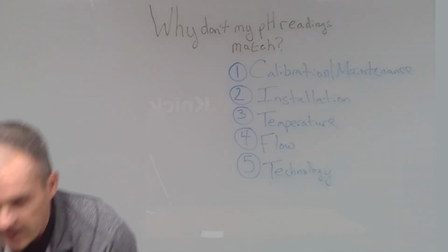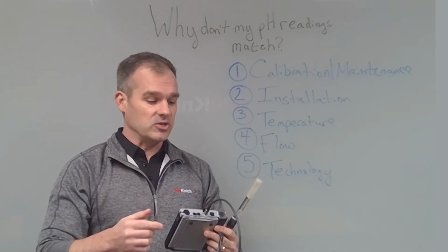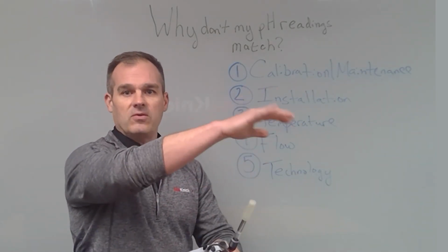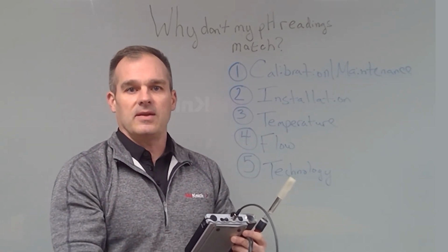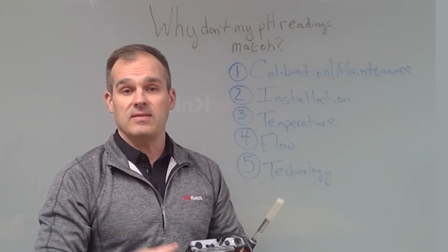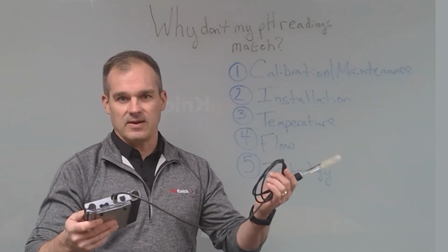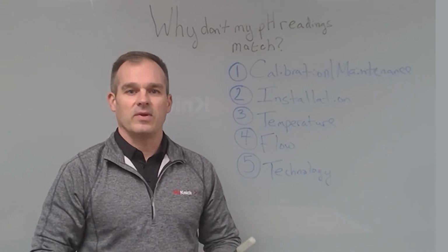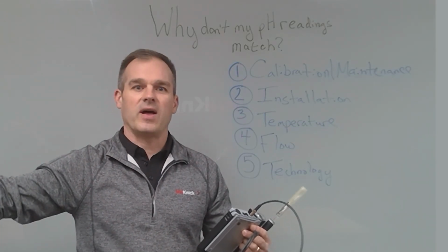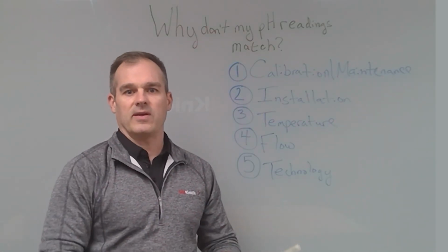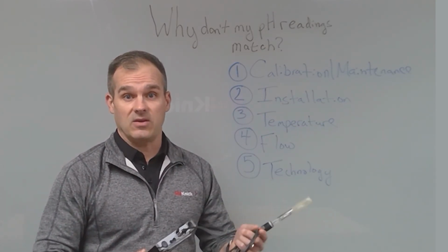And that's really where, for M4 Connect customers, the Portavo comes into play. We can eliminate a lot of these issues. We have MemoSense both in the field and with the portable. We can take the measurement right next to where the inline measurement is made, the sample, and it's portable, it's easy, you can take it in an electrically classified area. So we really recommend, even if you still are going to use those offline measurements, to use a Portavo as another way to validate which one of those sensors is accurate.